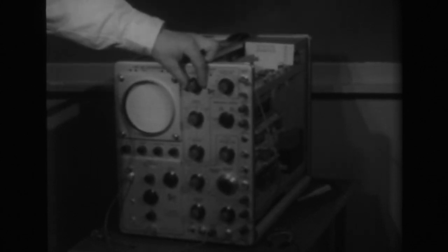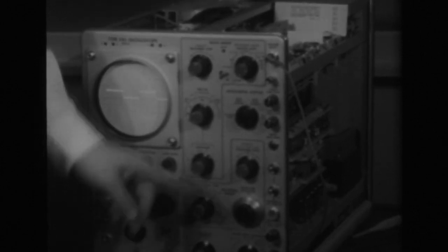Next, turn the calibrator on and adjust for the volts position, and set the output voltage at 200 millivolts peak to peak. Now, by carefully turning the triggering level control, you should be able to obtain a stable square wave on the face of the cathode ray tube, showing that the scope meets catalog specifications, which says that 200 millivolts fed in externally should produce a stable trace.